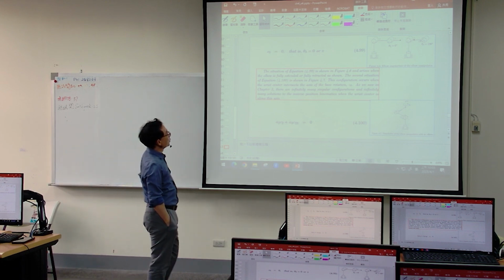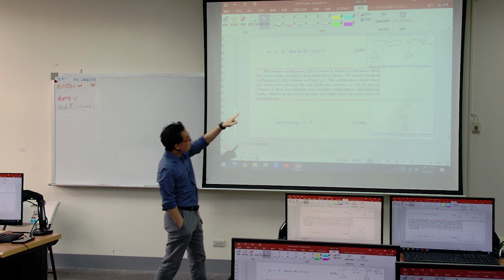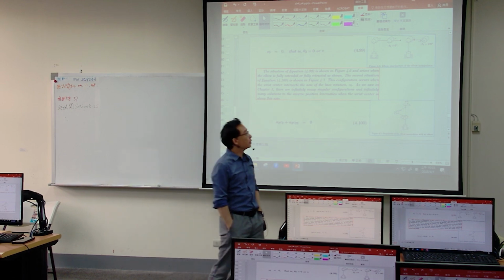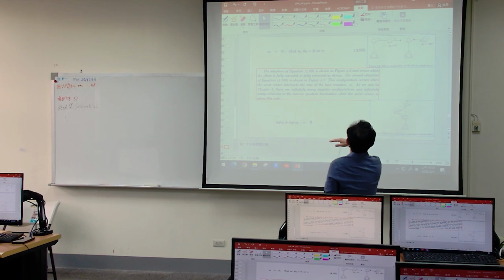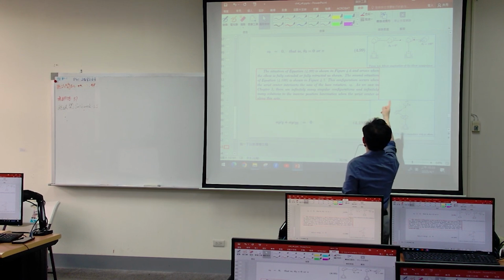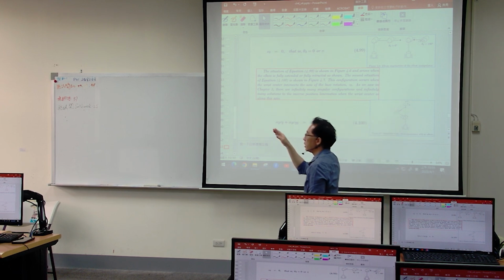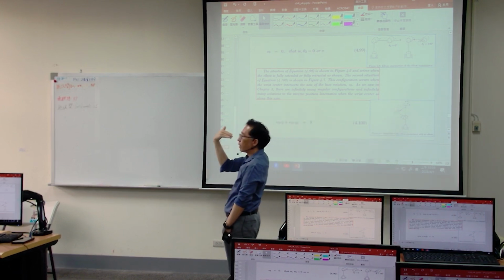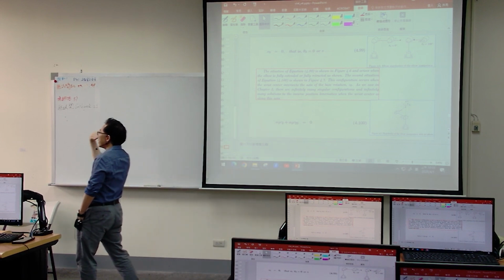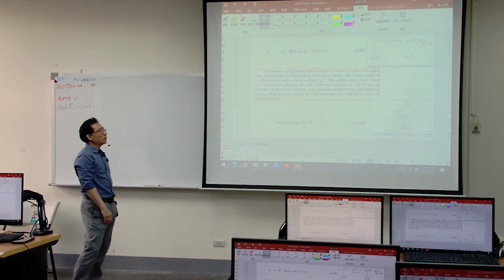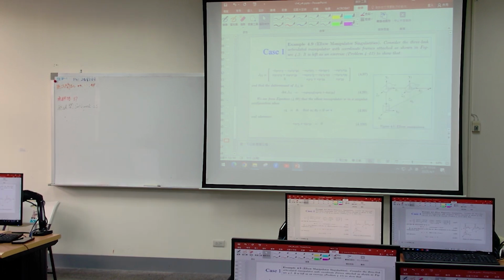theta equal to 0 or pi is the first posture. If your posture is like a cobra, and the last arm, theta 3, points out and points back, it means theta equals 0 and theta equals pi, then it becomes a singularity. The other condition is A2 C2 plus A3 C23 equal to 0.